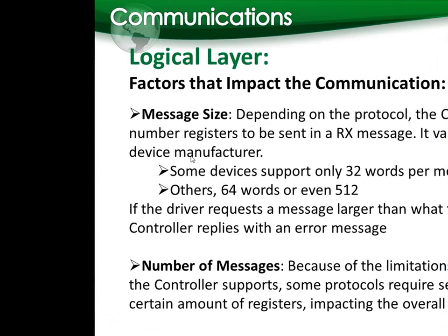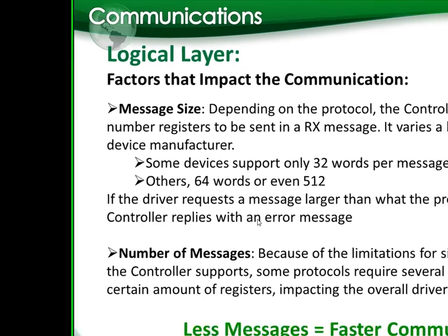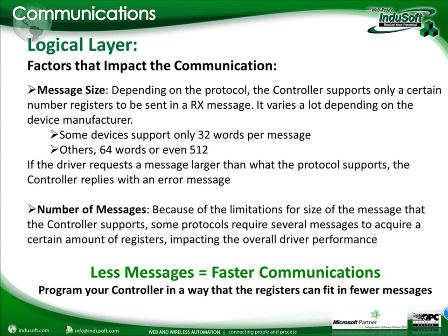So, depending on how much data you want to exchange with the PLC, you're going to have multiple messages, because you will not be able to fit all the data that you want in just one message. All right? So that's why I highly recommend, when programming your PLC, to think about the HMI as well, because the fewer messages we exchange with the PLC, the faster the communication will be.